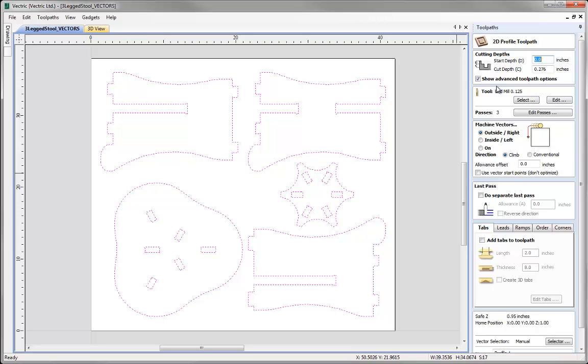particular tutorial. So with that checked, we're going to come to the top of the form here, and we have the start depth and the cut depth. Now these are not absolute values, so they're effectively always going to be measured relative to the material because they're depths from the top of the material. So even though we've set our Z0 to be up at the bottom of the block, once we get into the cutting depths themselves, these are just relative values to the material.